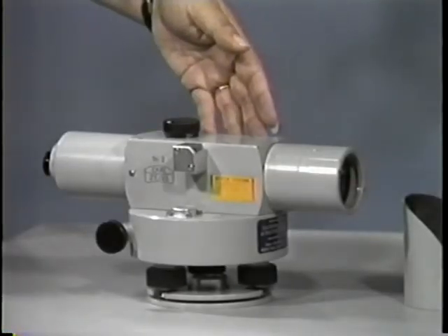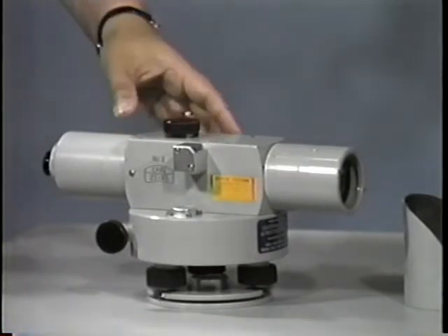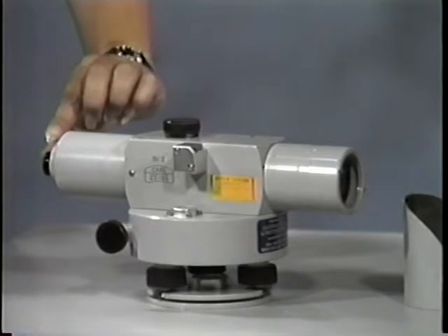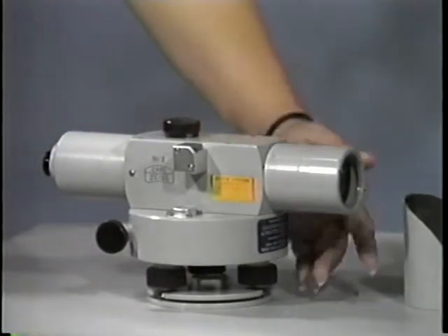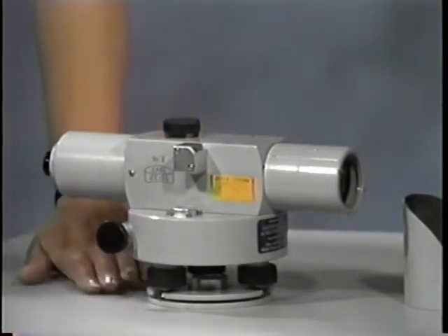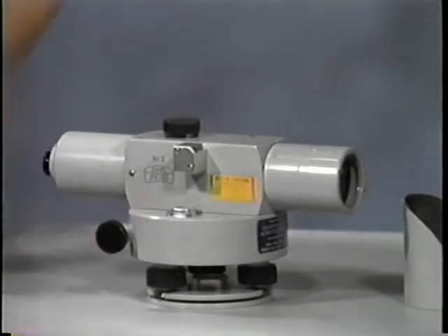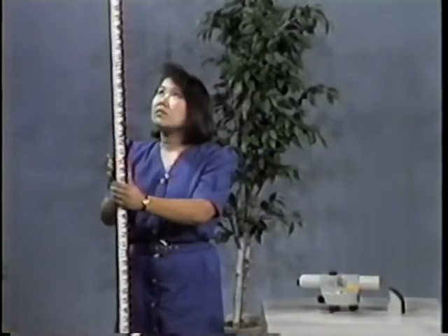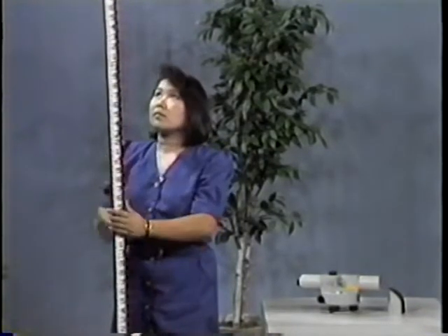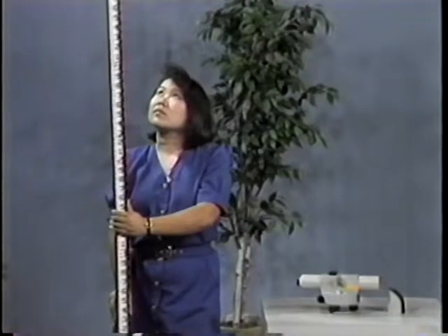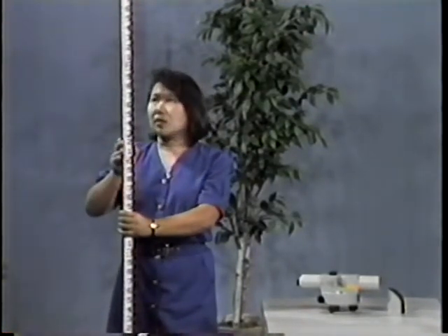This is a Zeiss Ni2 level. It is a typical pendulum level normally used with Philadelphia rods. It has an eyepiece with an objective lens and focusing adjustment. There are 3 level screws used in leveling the instrument. There is a bubble level used to level the instrument more precisely. The Philly rod is a 2-piece wooden rod with graduation marks in feet, tenths, and hundredths. Unextended, it can be read to a height of 7 feet. For heights greater than 7 feet, the additional section can be raised and clamped in place.